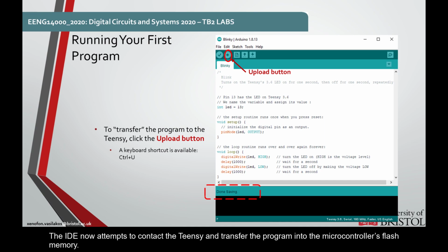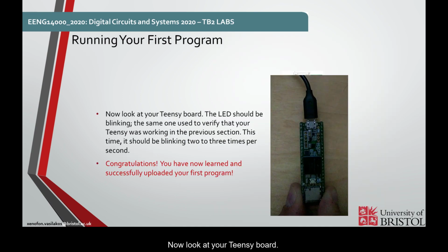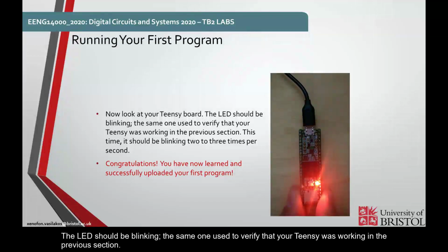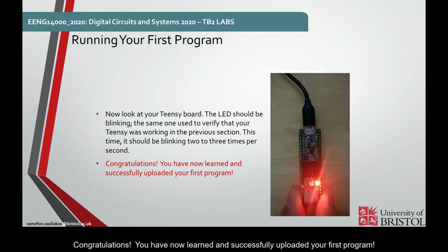The IDE now attempts to contact the Teensy and transfer the program into the microcontroller's flash memory. A message at the bottom should soon display the text "Done uploading." Now look at the Teensy board. Click the button. The LED should be blinking, the same one used to verify that your Teensy was working in the previous section. Congratulations! You have now learned and successfully uploaded your first program.